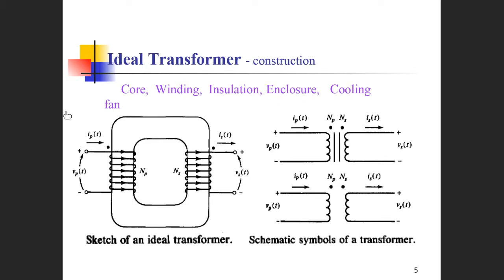There are cooling systems inside the transformers, because the transformers run at full load with big currents. Due to the internal resistance of the transformer's coils, there are some power losses. Also, due to the resistance of the cores, there are some core losses. So the core losses and the copper losses make the temperature of the transformer as a whole higher, generally up to 70 or 80 degrees.